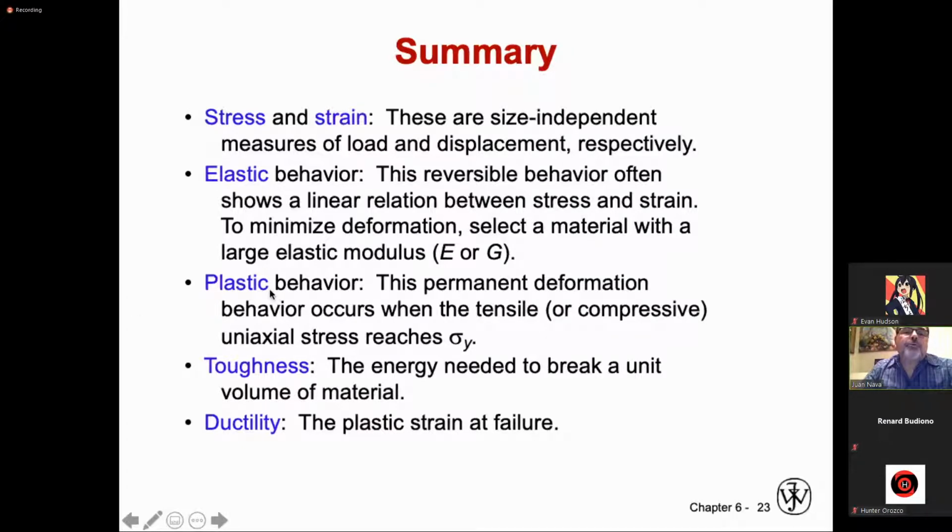Plastic behavior, to the contrary, means your deformation will remain permanent. Plastic deformation will lead to a strengthening of the material, and plastic deformation is only possible because you have dislocations as defects in your steel or material bulk. By plastic deformation, the moment you reach that regime of deformation, there is always a component that is tangential to the force that you're applying. That will be the force required to activate your slip systems, that will let your dislocations move and multiply, and that will make it possible for you to execute plastic deformation.